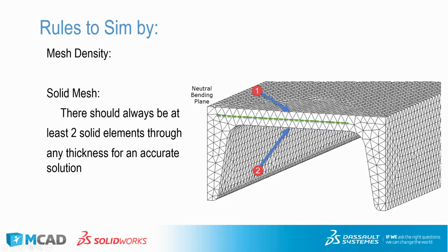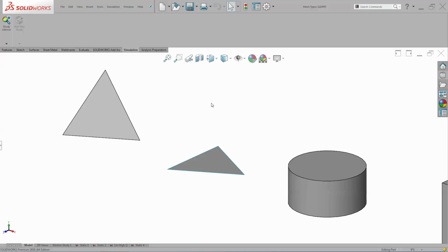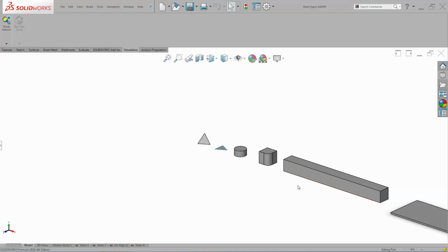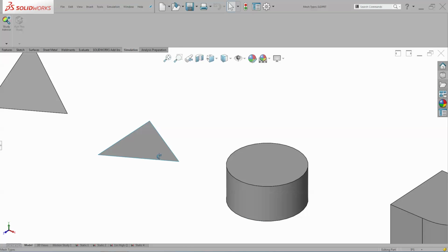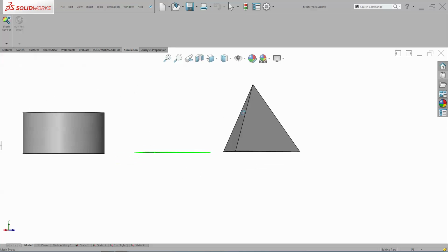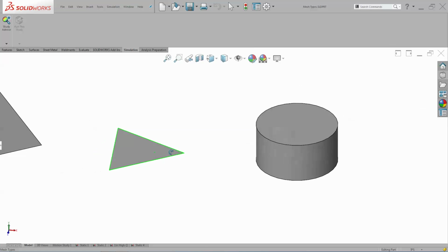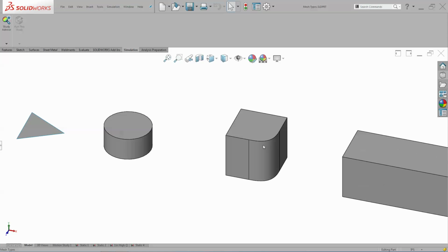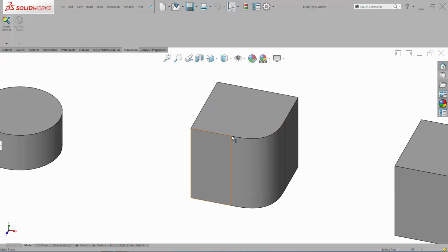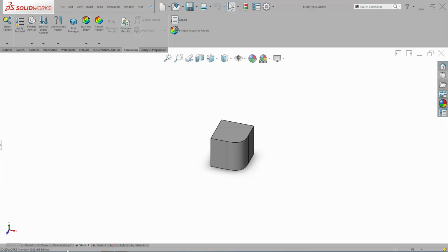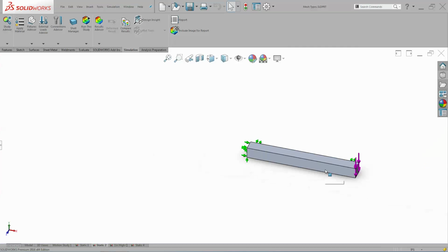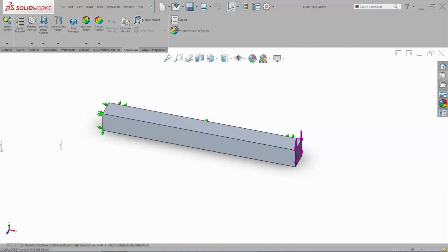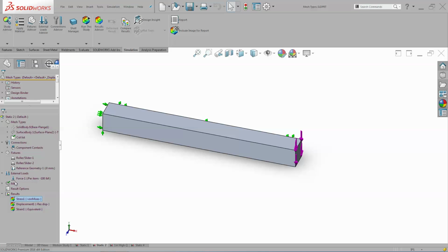Now, when we're looking at mesh qualities, let's take a look here back in SolidWorks. Just to start out, here are our basic shapes of what kind of meshes we've got. It's a tetrahedral on the left, with a 2D shell in the middle, and then a beam element right there. Some simple illustrations. If we take a look at this next piece over, we've got this beam here.